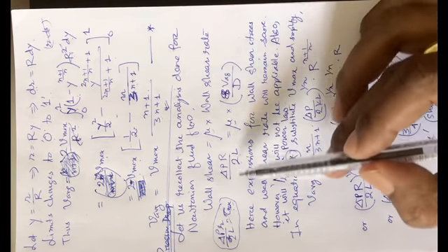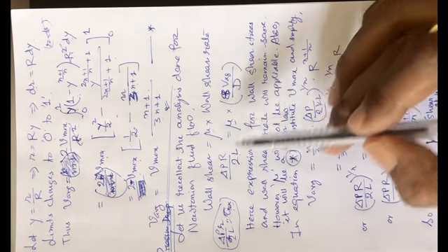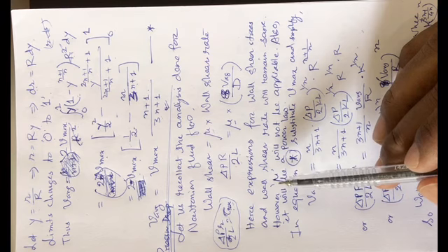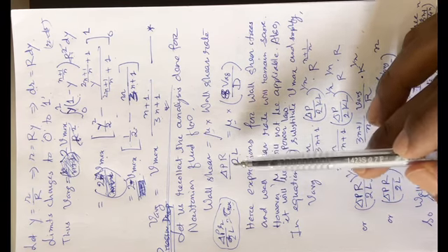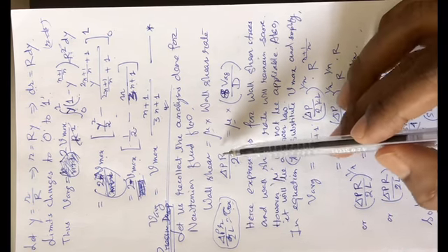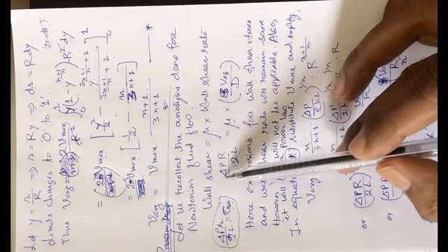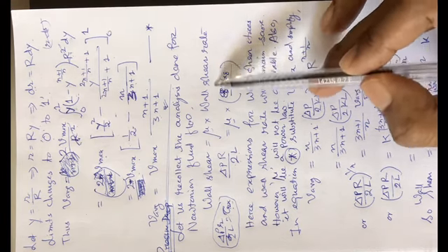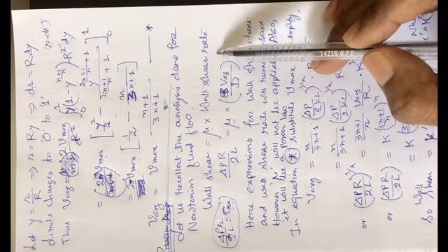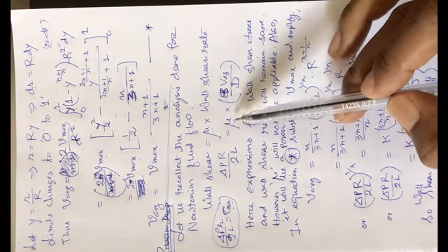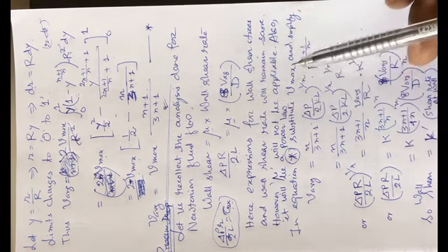Now you can recollect that this shear stress is equal to mu multiplied by the wall shear rate. Now we are talking about non-Newtonian fluid. So what we will be expecting is that we again have wall shear and wall shear rate, but here the power should be n, and then what should be the equivalent term for this mu?